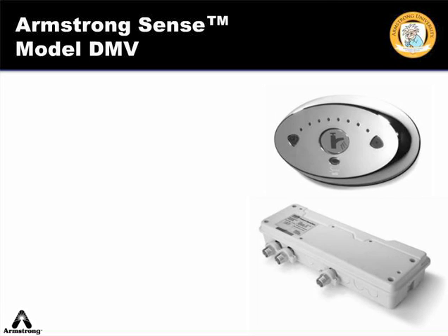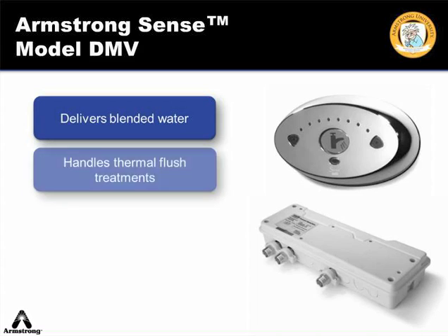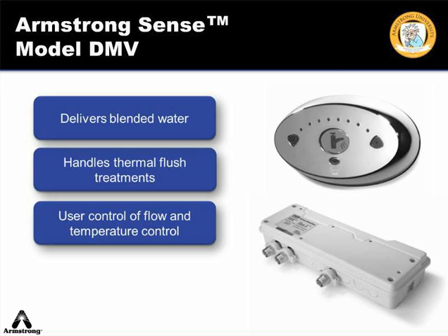Another way to control water temperature at the point of use is with Armstrong's point-of-use Sense line of water temperature control products. It is a digital device that safely delivers blended water to the user and is also programmed to handle thermal flush treatments from generation all the way through point of use. Armstrong's Sense system is a series of 4 individual digital mixing valves designed for installation at the point of use to allow user control of water temperature and flow.